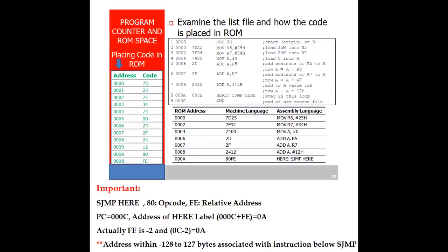Okay, after that, the last instruction. You see that as we have already learned in the case of the microprocessor, there was one halt command, but here in the case of the 8051, there is no such halt command, no such end command. The command we are finding is actually a pseudo instruction. Actually it is a directive of the software, ORG 00 hex, END. END means it is a software directive. Whatever instruction is written after END will not be executed. So it is the assembler directive.